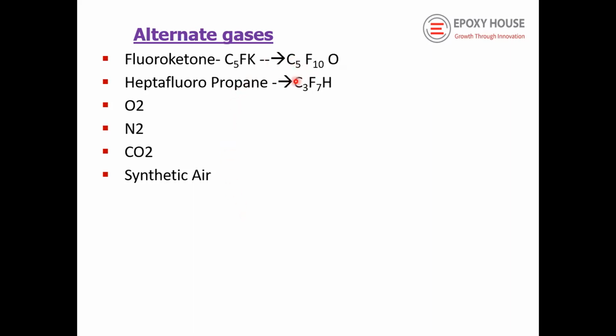These are the few gases, and fluoronitrile is also another gas, which is used for essentially the same application. See, nowadays there is medium voltage gas insulated switchgear also. People have tried, because the circuit breaker is already used with a vacuum interrupter, and the gas around the circuit breaker, disconnector switch, earth switch and all can be used with any of the gases with a higher positive pressure.